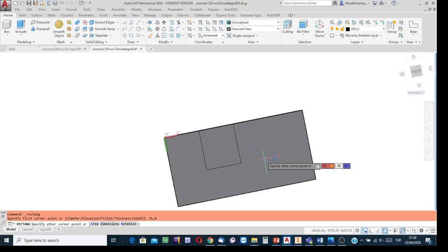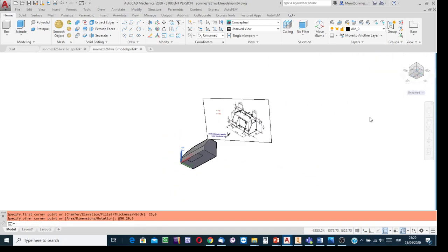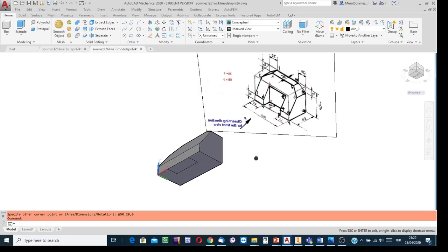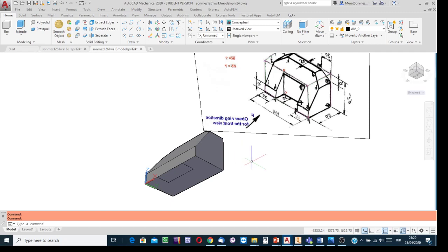And the z value, of course, must be written, since unexpectedly I had a fourth box. Click the comma key and write 0 into that box, because the z value is 0, because the sketch is on the XY plane. Press enter and create the rectangle. I don't know why I had the fourth box. By mistake I think I made one more click.